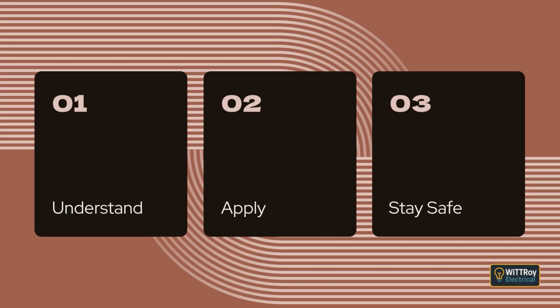Clause 3.14 explains that wiring systems used for safety services must follow every requirement in this section, and must also follow the extra rules in Section 7.2, because safety systems must remain reliable during faults and emergencies. Clause 3.15 explains busways, including rising main systems. These systems must meet the requirements of AS/NZS 3439.2 and be installed exactly according to the manufacturer's instructions. Whenever a busway passes through a fire-rated part of a building, it must also meet the fire penetration requirements described in Clause 3.9.9.3 so that the integrity of the fire barrier is not reduced.